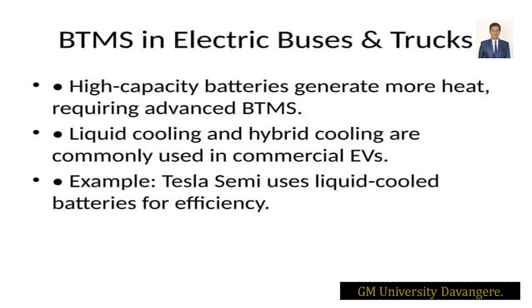The heat generation: how is the heat generated in the electric vehicle for the 400 kilowatt-hour battery, at 50 kilowatt of charge, right? And also see the daily cycles, how many cycles are reduced per day. You have to think about the downtime cost also. What is the cost for the vehicles during downtime, right? And also you have to think about the pack weight, and the BTMS power which is drawn, where it is drawing a power of 1.1 to 2.2 kilowatts, isn't it?